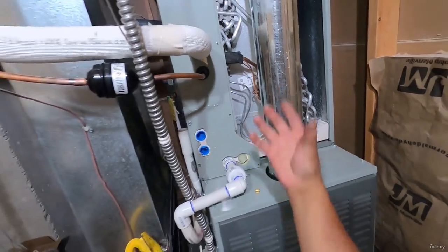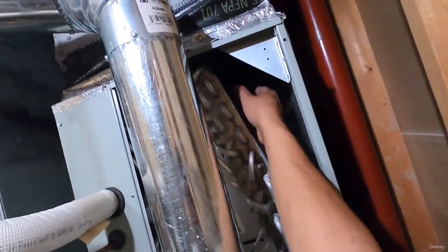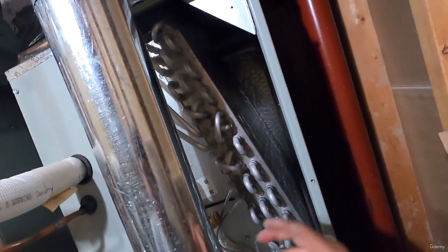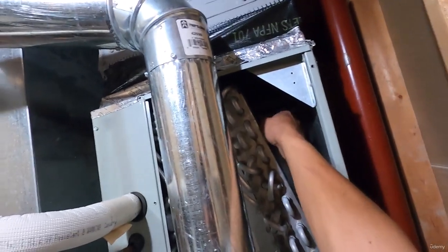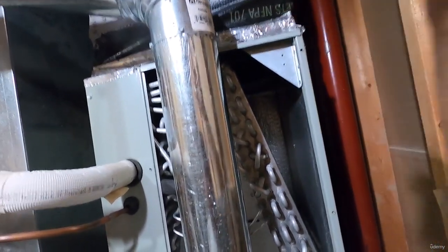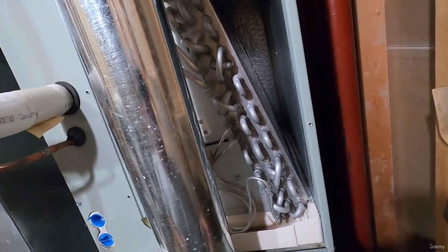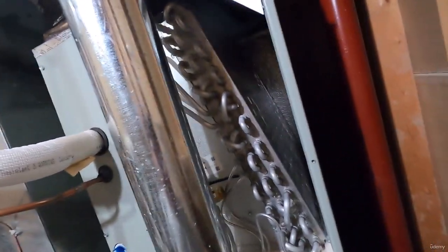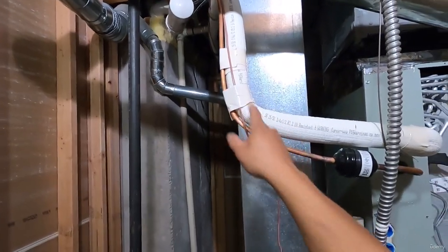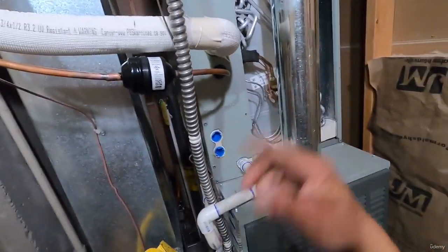So it enters the bottom, warm air, and as it flows across the coil, the Freon in the coil is absorbing the heat from the air. So when that air exits, a lot of heat has been taken out, and that's the coolness that you feel through the ducts and through the return or the supply registers. And that heat is then taken on the low side back to the compressor, and it just keeps pumping it all back, back and forth, back and forth.